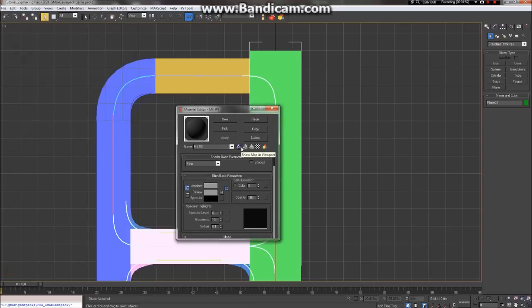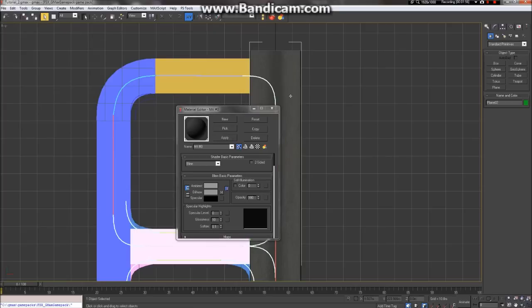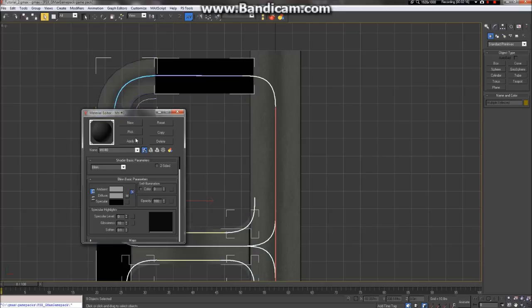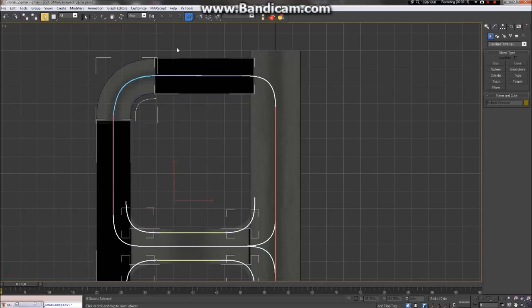So we're just going to load this texture here. We're going to click the checkered cube and say apply. And it's applied to our plane here. In fact, let's go ahead and apply it to the rest of our planes. And we'll also apply it to our lofts. I'm just holding down the control key to select all of them at once. That looks good, I think.